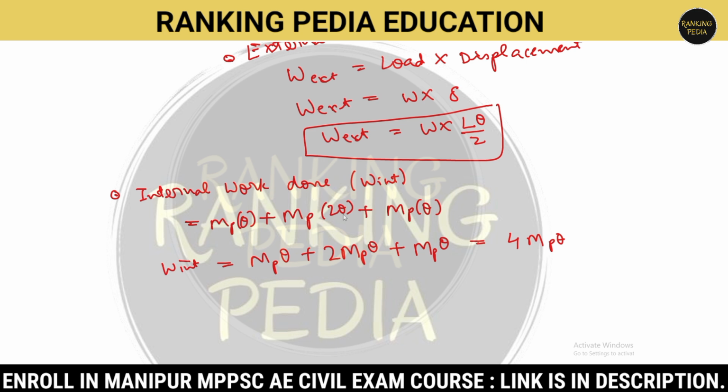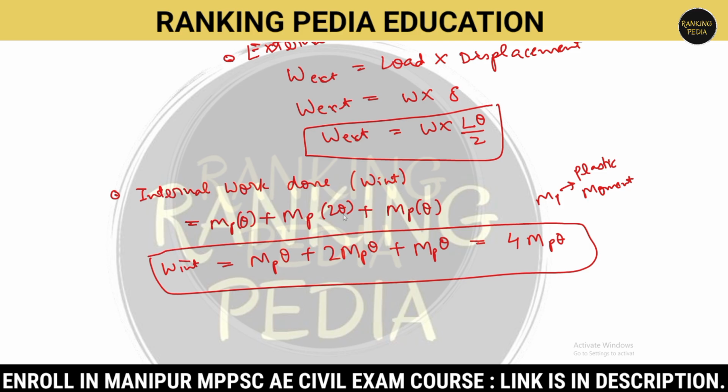Now here, what is Mp? Plastic moment. So we have calculated external work done. We have also calculated internal work done, which is 4 times of plastic moment.